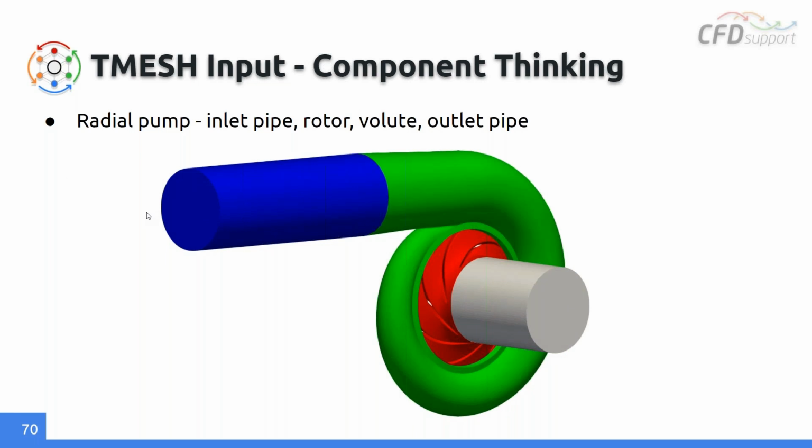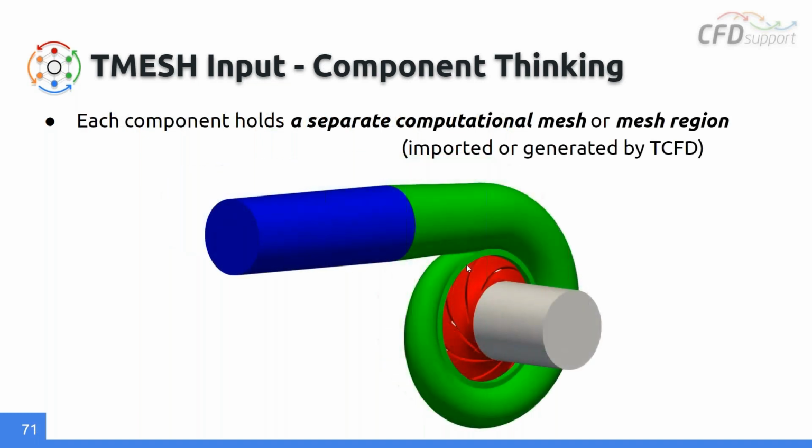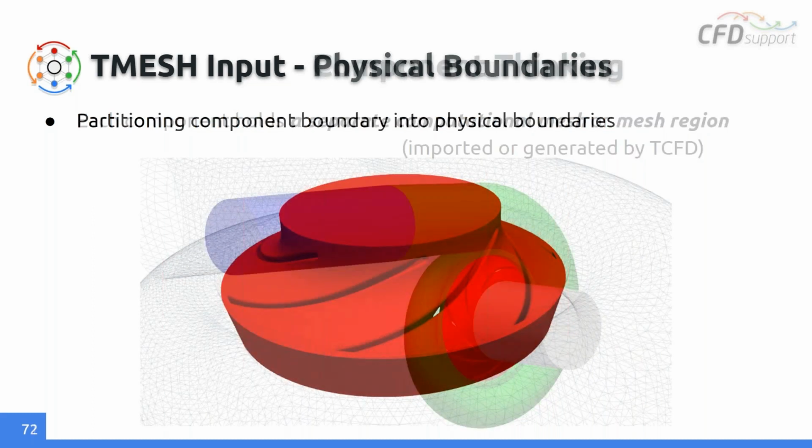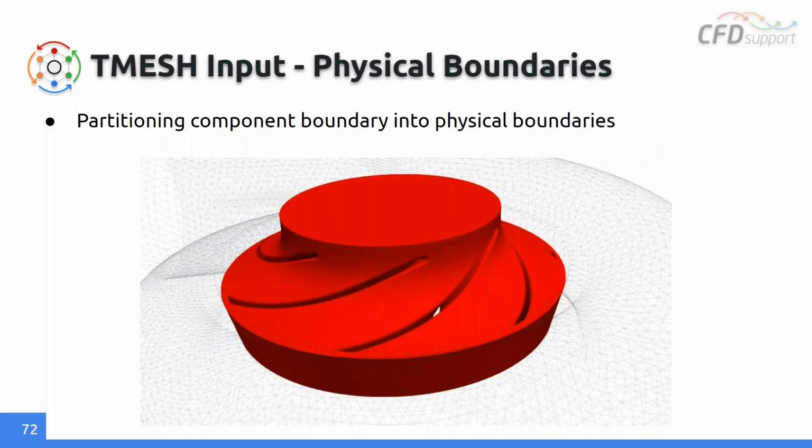So when preparing the STLs, you also have to prepare all the parts, mainly the interfaces, which are not part of the CAD because there are no solids dividing these parts. So interfaces have to be added and exported separately. Then each part is defined as one STL, because the STL also defines the patches of the part in the computational domain, and each part has to be assigned a special boundary condition to define the CFD problem properly.